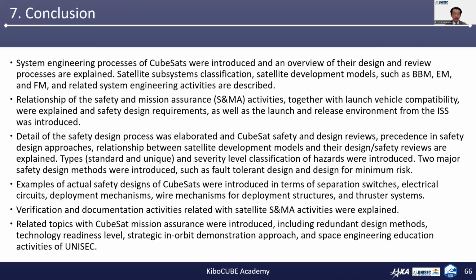Details of the safety design process were elaborated, and CubeSat safety and design reviews, precedence in safety design approaches, and the relationship between satellite development models and their design and safety reviews were explained. Types and severity level classification of hazards were introduced.